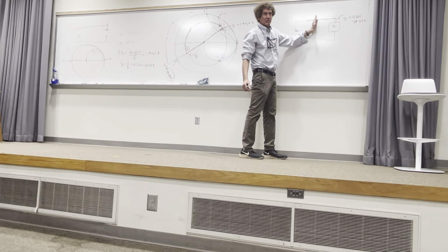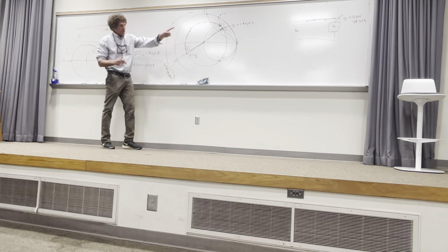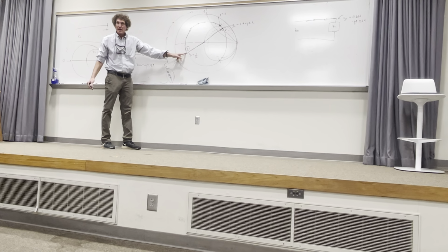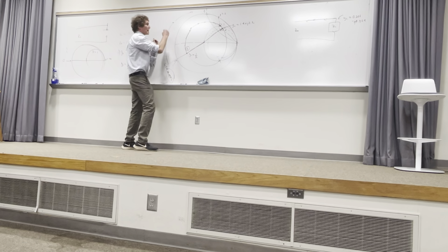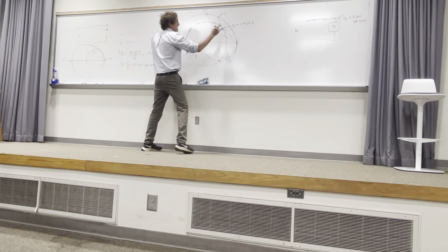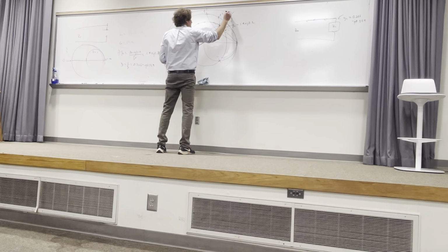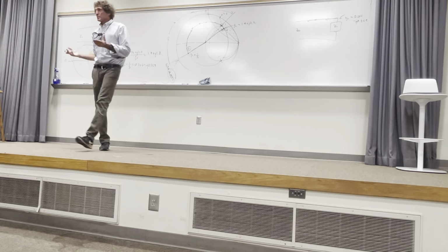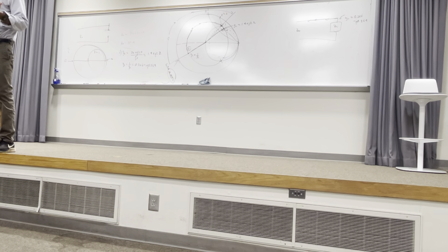Y'all hear me? It's in parallel though, remember. So here's where we came in at, and I'm going back to that. I'm right here, right? Y'all with me? If I move from here to this point right here, that's the shortest distance possible to get to the 1 plus or minus jx, right? So that will be the position that I'm going to put the shunt on. Everybody with me on that?